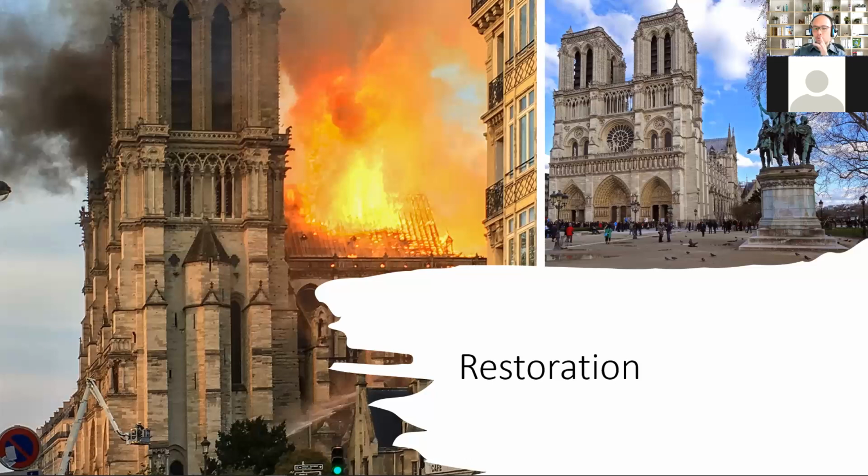Restoration processes involve removing materials and layers of changes that may have been added in order to clarify the original design intent or architectural style or association with a significant historic event or significant historic or famous person. In some cases, materials and changes that may have become significant in their own right are removed to more accurately reflect an earlier period. As a result, restoration processes can be the most invasive of these primary historic preservation strategies.